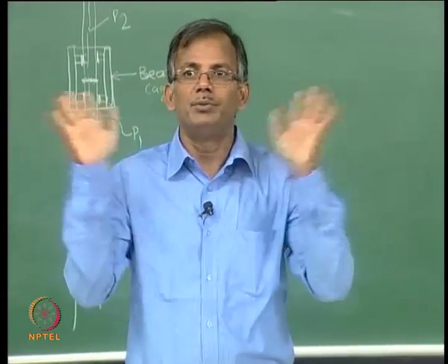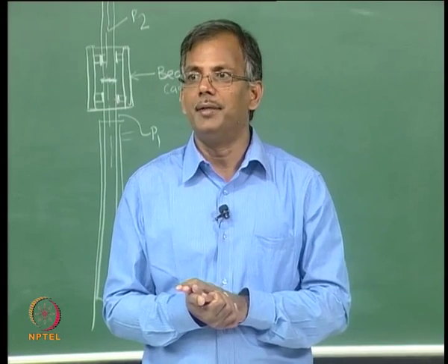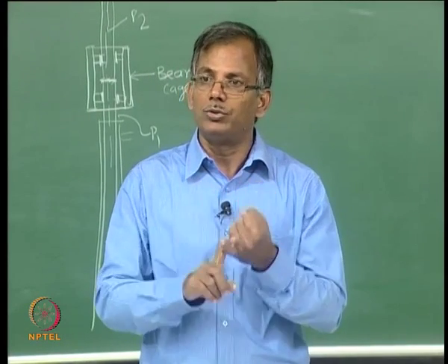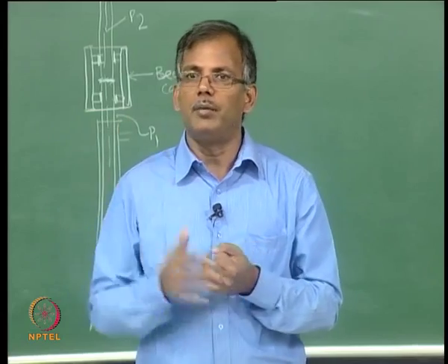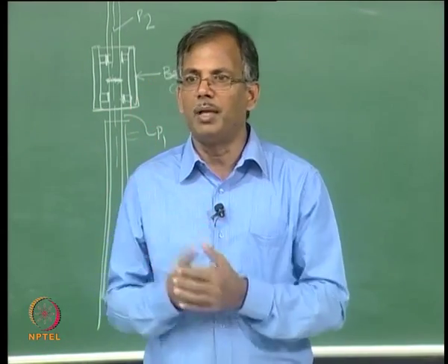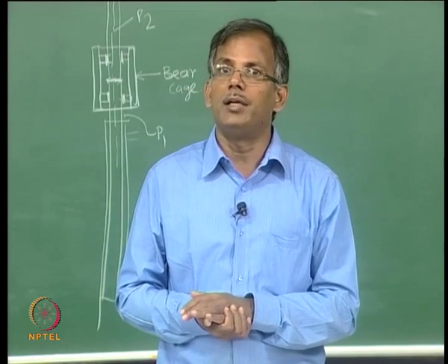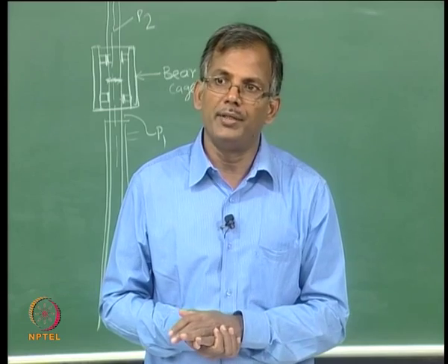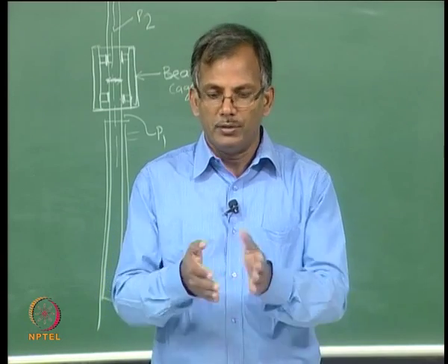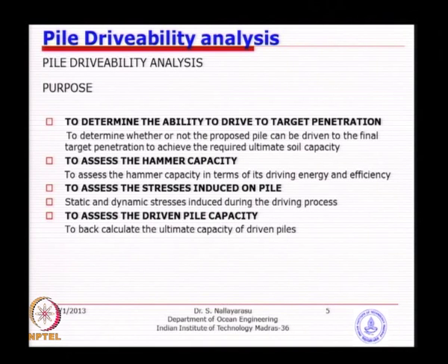All your engineering becomes of no use, because you have tested the pile in reality. So, such things are possible onshore, definitely 100%. Coastal, maybe yes, maybe no, depending on water depth. Sometimes we do, sometimes we cannot, because if the water depth becomes larger, testing in coastal areas also becomes a problem. But definitely for offshore, we will not be able to do testing, because the reaction frame cannot be constructed. The main problem is the reaction frame.